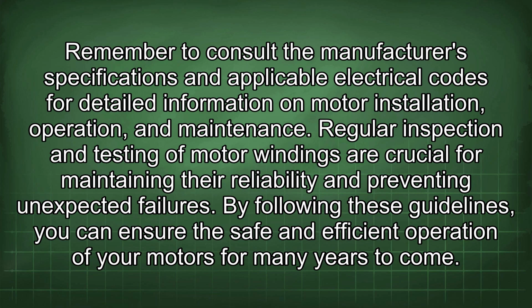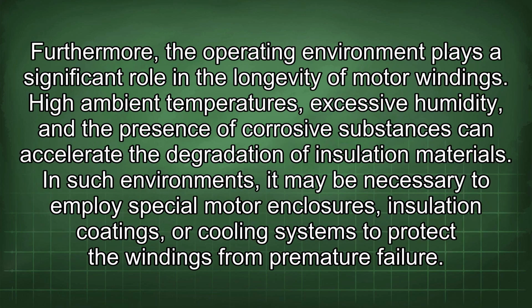Regular inspection and testing of motor windings are crucial for maintaining their reliability and preventing unexpected failures. By following these guidelines, you can ensure the safe and efficient operation of your motors for many years to come. Furthermore, the operating environment plays a significant role in the longevity of motor windings. High ambient temperatures, excessive humidity, and the presence of corrosive substances can accelerate the degradation of insulation materials.